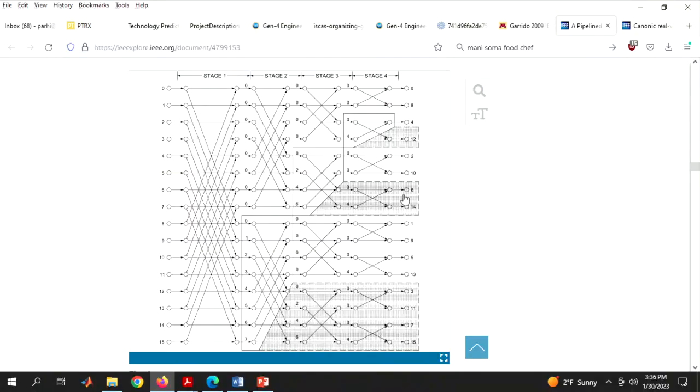Okay, so instead of trying to say, okay, we will compute coefficients 0 to N by 2, and then not compute the remaining parts because they're conjugate symmetric, here the argument is, let's throw out the computation of these redundant parts. If you look at it, 12 is conjugate of 4, so that means I don't really need to compute that half a butterfly.